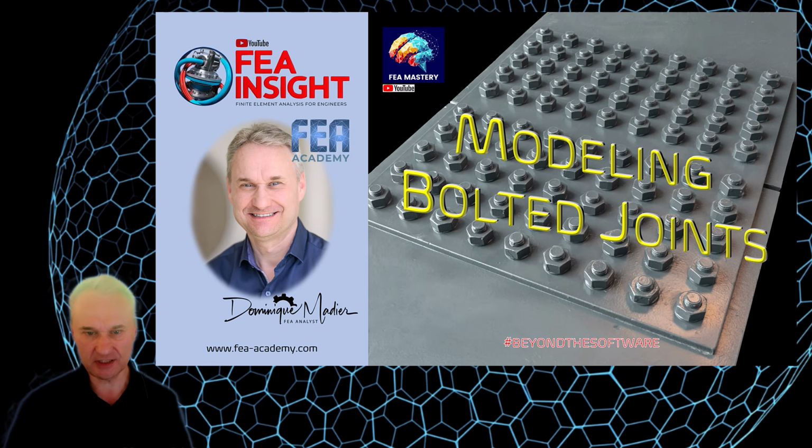So the components can be joined using three different approaches. First, the bolted joint, the welding, but also the bonded joint. The bolted joint is by far the preferred solution for joining two components. However, welds are also intensively used. On the other hand, the bonded joints are used to build composite structures like carbon monolithic, sandwich honeycomb. In those cases, the bonded joints are used.